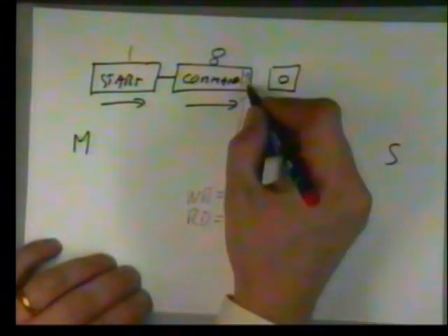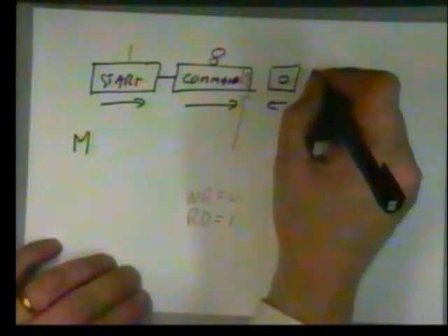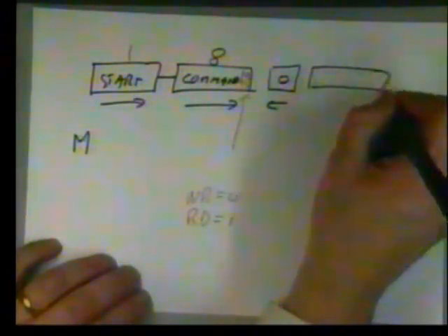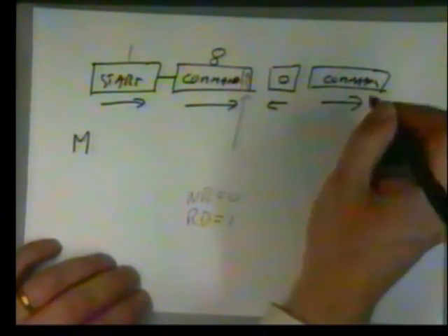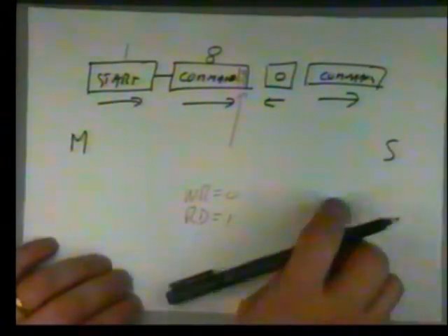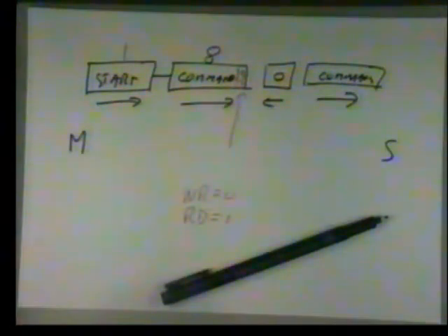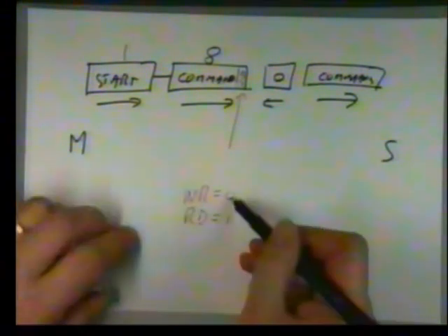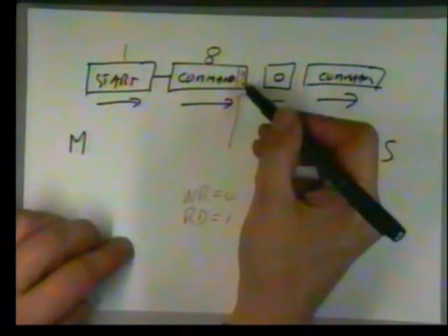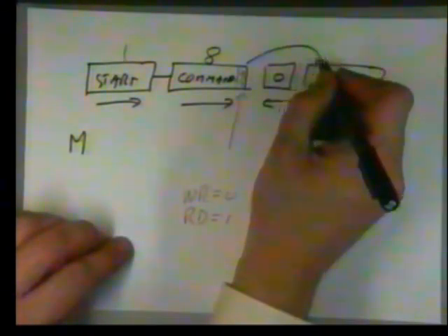If it was a write operation, then the next thing that would happen is that another command would go off in that direction. So a second command is instructed by the fact that there was a write, a logic level 0, in the least significant bit of the last byte that was written. So really that's telling us what happens next.